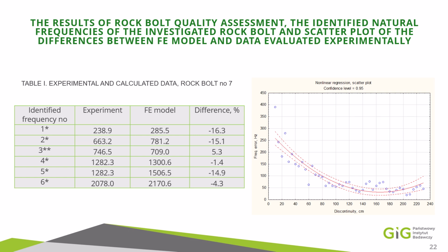Then the problem is also with drilling methods: in hard rocks, the diameter of the hole may be larger than projected, and because of that the amount of grout inserted is not enough for proper connection of the rock bolt to the rock strata, and may lead to lack of grout in that lower part of the rock bolt.